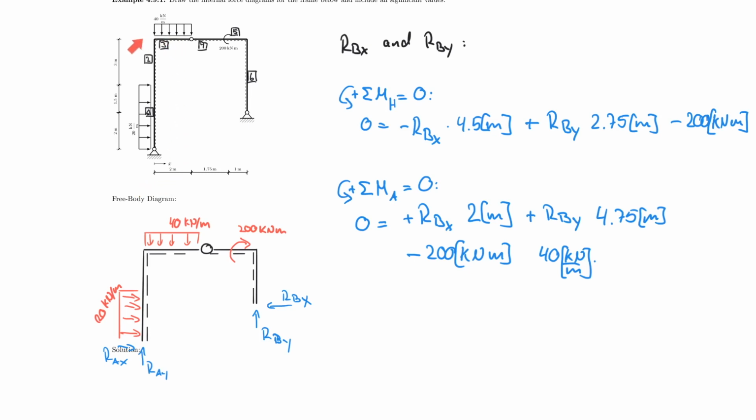From here to here is 2 meters. And then I also turn about this point, so actually I have a lever arm of 1. So times 2 meters multiplied by 1 meter. Now I have to decide, is it clockwise or counterclockwise? And again, this force here is rotating this way around about point A, so therefore it's clockwise, and that is negative.